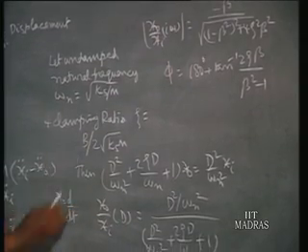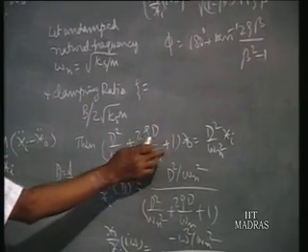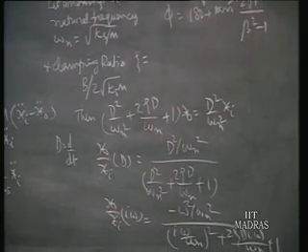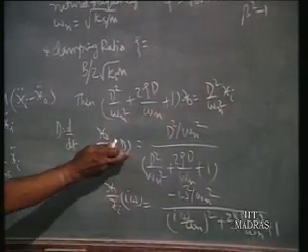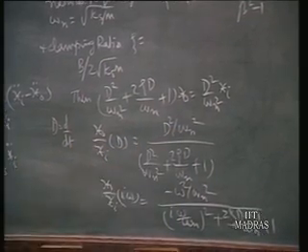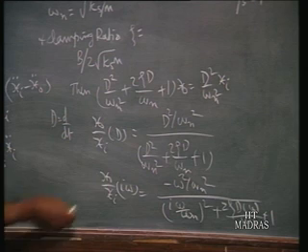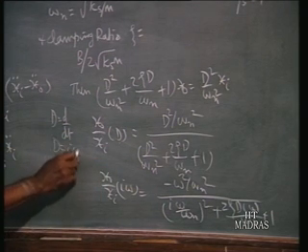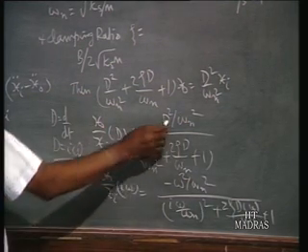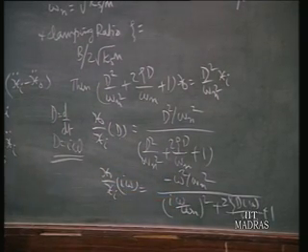Then substituting these terms in this equation, we arrive at this equation: D squared by omega n squared plus 2 psi D by omega n plus 1, into xo, is equal to D squared over omega n squared into xi. Now, arranging these terms, xo by xi in terms of the differential operator D, you receive this equation. Now, to find the frequency response of this setup, substitute D by i omega. That is our standard method of finding frequency response. So, putting i omega, minus i omega squared whole squared is equal to minus 1. So, you got this equation.